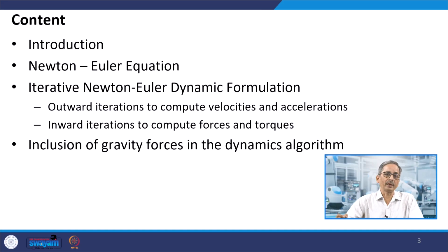I begin with the introduction of this topic, then we will see the Newton-Euler equation, and we will see that these equations are iterative in nature. Initially we go outward from the base frame to compute the velocities and accelerations, up to the end effector, and then we come back from the end effector to the base frame, which we call the inward iteration, to compute the forces and torques.